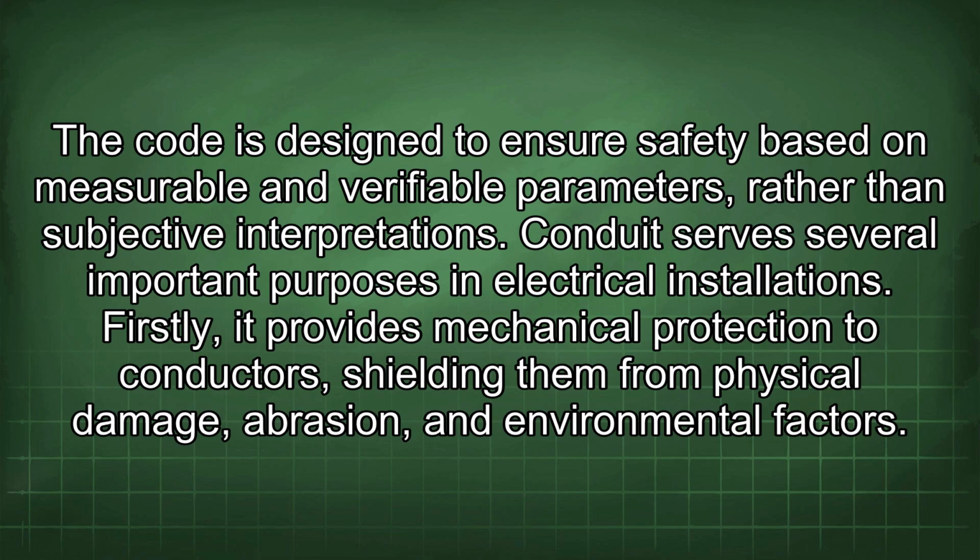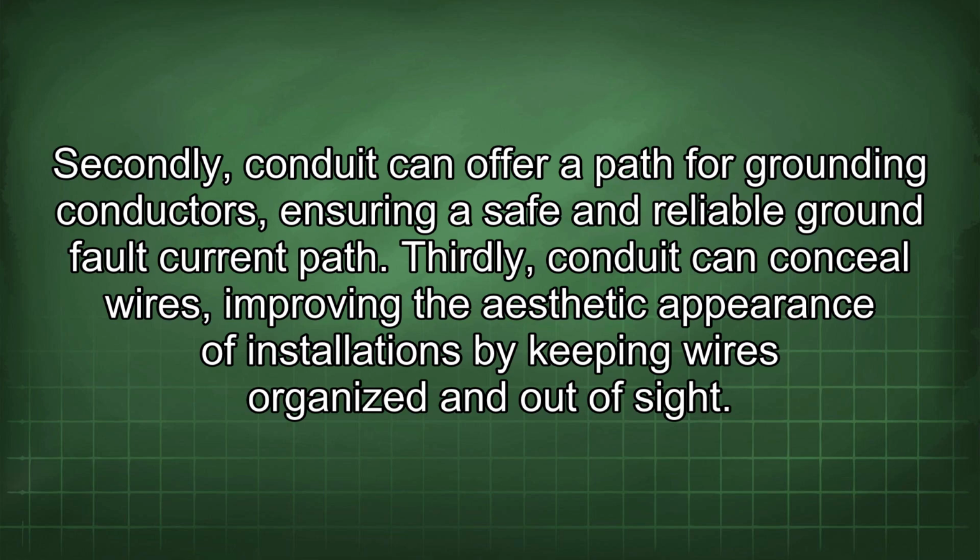Conduit serves several important purposes in electrical installations. Firstly, it provides mechanical protection to conductors, shielding them from physical damage, abrasion, and environmental factors. Secondly, conduit can offer a path for grounding conductors, ensuring a safe and reliable ground fault current path. Thirdly, conduit can conceal wires, improving the aesthetic appearance of installations by keeping wires organized and out of sight.